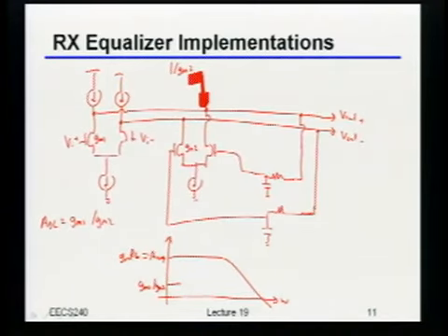Okay, so now let's just call this R and C, and of course that's also R and that's also C. At what frequency would you start to get a gain that's different than that out of this closed loop structure here? 1 over RC, right? Because once you hit that frequency, instead of this being diode connected through a gain of 1, it's going to be a gain of less than 1, right? And as you go up to higher frequency, the gain drops linearly with that frequency, right?